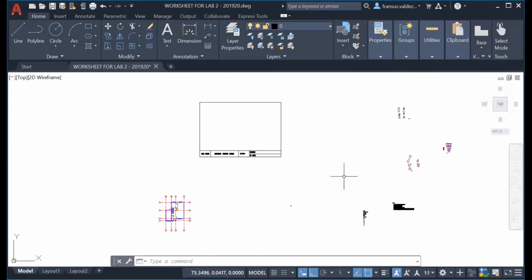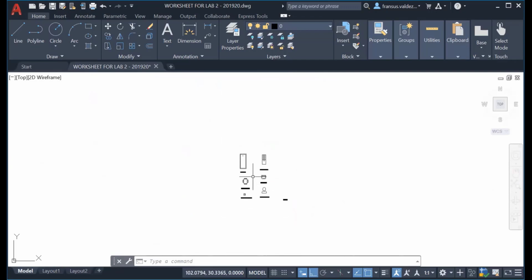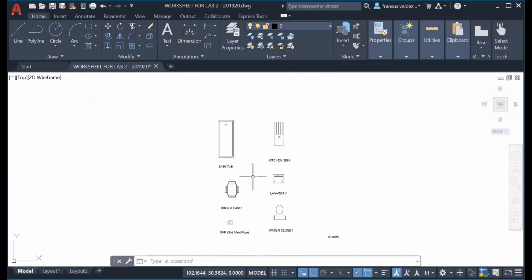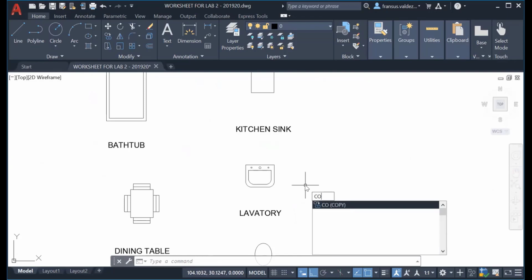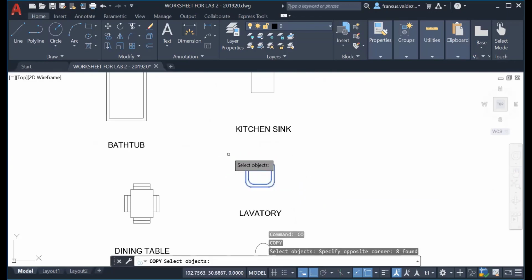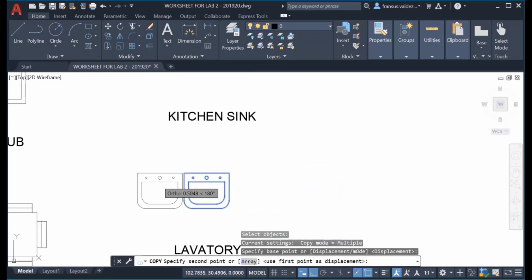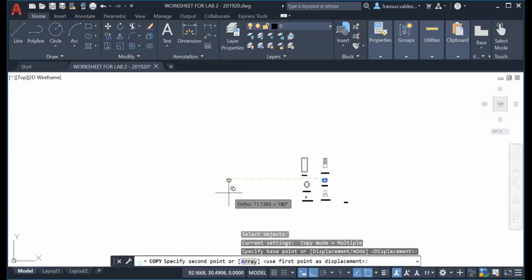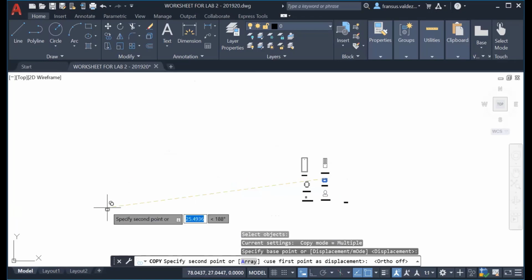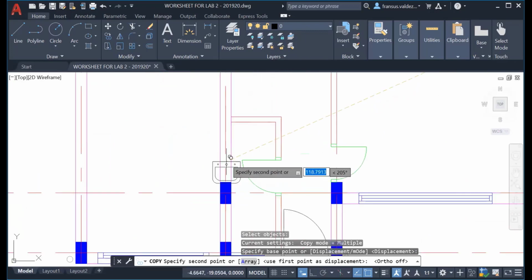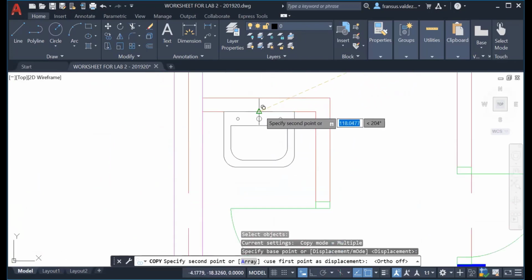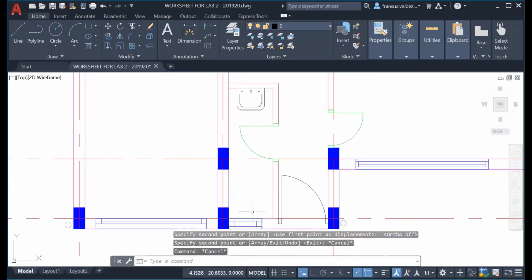All right. Now look at this here. When we put now the sanitary fittings, which we have already opened here, look at this one here. Now we need to copy this one and put it there on its position. So copy this one, copy. All right. Highlight this one here, and then grab it in the middle. Grab it in the middle, okay, and then click F8. Okay, all right, and then we can put it here. All right, so this one we find the middle. Okay, it goes.